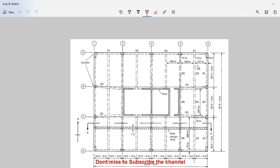This is the grid system they define, and the exterior panel is 157-inch clear. This is the clear span, and this beam is 14-inch wide, but the perimeter beam in the north-south direction is 16-inch wide.